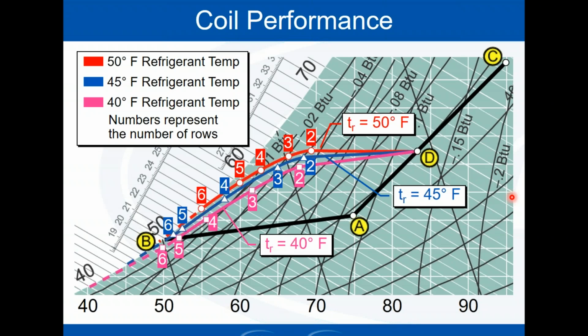The evaporator coil, condenser coil, and compression system would be designed around a specific refrigerant to get to a specific temperature. So whether I had a system that was R22 or 410A or 454B, if it was designed to give me 45-degree refrigerant temperature in blue, at that point, the air would not care. The air doesn't care what refrigerant got me to the 45-degree refrigerant temp. It just knows it has the 45-degree temp. But the choice of refrigerant might make it harder to get to the 45. So hopefully that answers that.